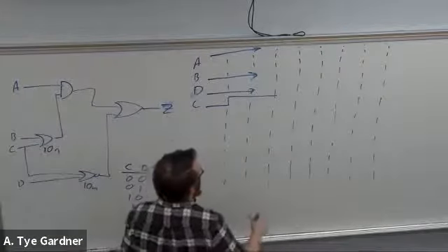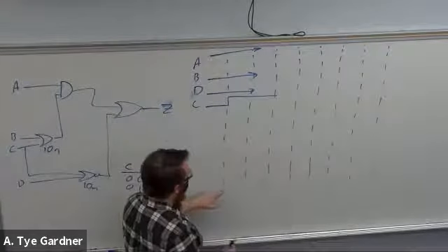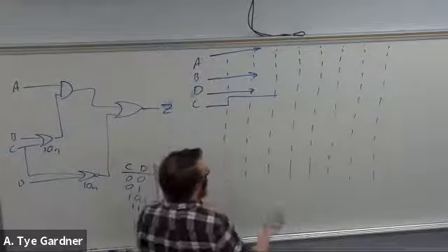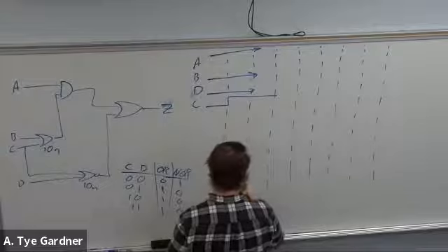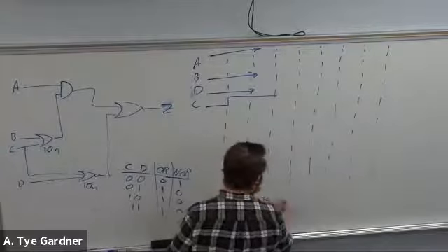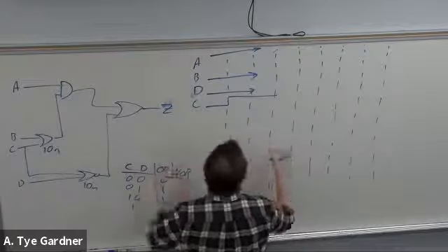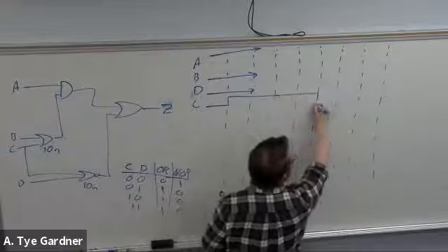So if I do both, I'll find the hazard. Okay. So how long is it going to take? There's 3 gate delays. If I call each one of these 10 nanoseconds, which I can, I want to just make sure there's time to settle. 10, 20, 30, 40. Okay, so if it's 3 gates, I need at least 1, 2, 3, and I'm going to call it 4 before I change.